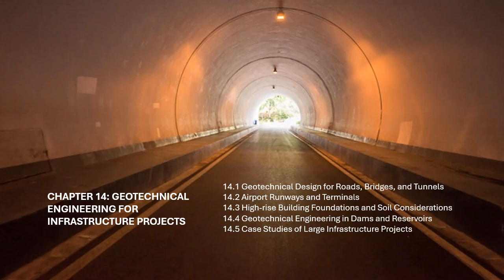Geotechnical considerations. Similar to earth-fill dams, the materials used for the rockfill must be stable and resistant to erosion. The design must ensure that the rockfill is compacted adequately to minimize settlement and maintain stability over time. Geotechnical engineers also focus on the internal drainage of the dam to ensure it remains free from water accumulation that could cause instability.